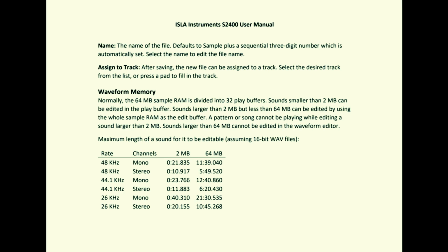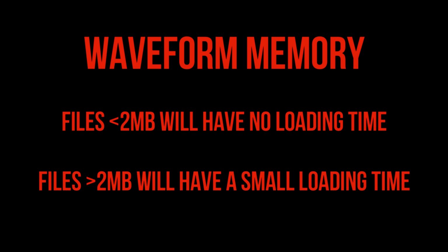A quick note on memory: a detailed explanation of waveform memory is found in the manual. But in simple terms, files smaller than 2 megabytes will have no loading time, but files larger than 2 megabytes but smaller than the maximum of 64 megabytes will have a small loading time. But once you're done editing, there's obviously no delay with triggering or playback.